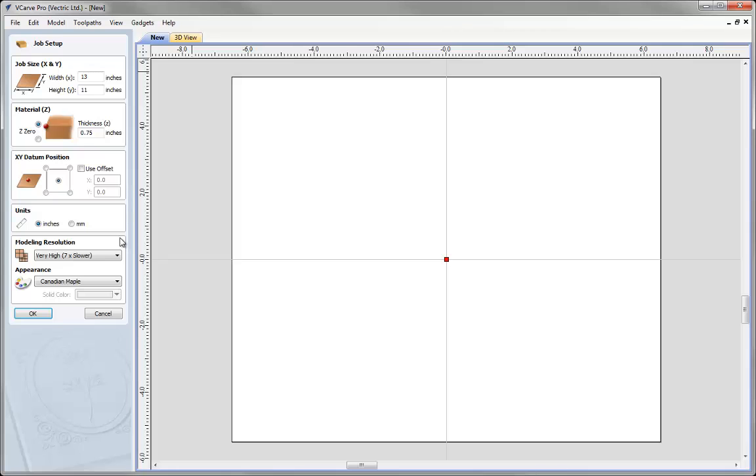The settings we have by default, if we click on the down arrow here, you can see a standard, high and very high. The more you use, the slower some calculations are going to take, so you just need to be aware of that. For the vast majority of parts, I'd recommend going with high or very high as being reasonable. If you did find that you could see some degradation of edge quality on your 3D jobs and you wanted to go to even higher settings but with a much bigger penalty for how much slower they'll be to